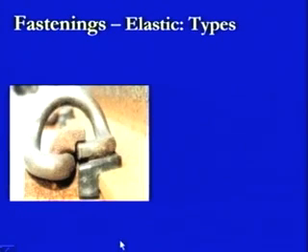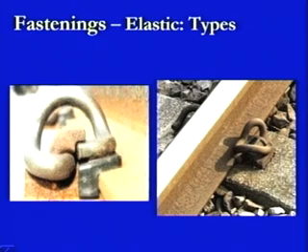This is one photograph where the Pandrol clip has been shown, and this is another one. Here we can easily see the shape of the part provided at the bottom through which this clip is moving, and there is a plate provided here, and this section is coming and putting the toe load of 700 and something kg at this position. Because of this shape, it is in a position to put this much pressure at this location, and that is how it maintains this rail section in position.